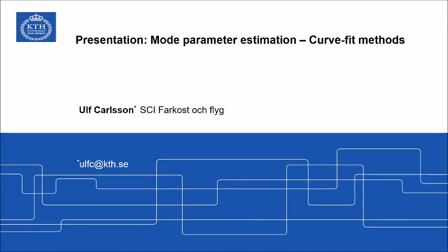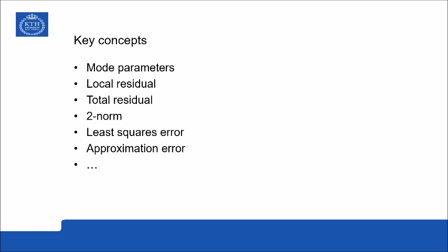In this presentation I will talk about the most commonly or frequently used mode parameter estimation methods, which is the curve fitting methods. So we will meet some key concepts, mode parameters, which are not new but will be repeated here. Then we will introduce two new concepts, which are local residual and total residual. And we will use the 2 norm, and we will also introduce least squares errors and a concept we call the approximation error.